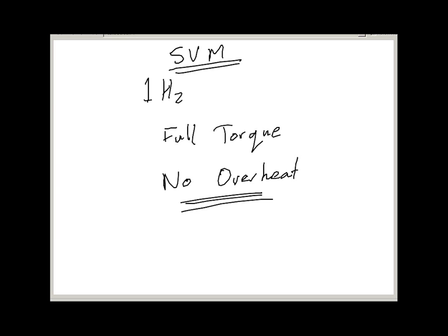They told me they then phoned up the VSD's rep and told him what they'd done, and the rep had no idea that you could even do it. So that's something to be aware of. But this really, really does work. If you use this space vector modulation or voltage modulation or whatever it is called for your manufacturer, then you will drop the temperature of the VSD motor, and you'll be able to run it less than 15 hertz. And because you're not putting the extra energy in, you're not getting the extra heat out.